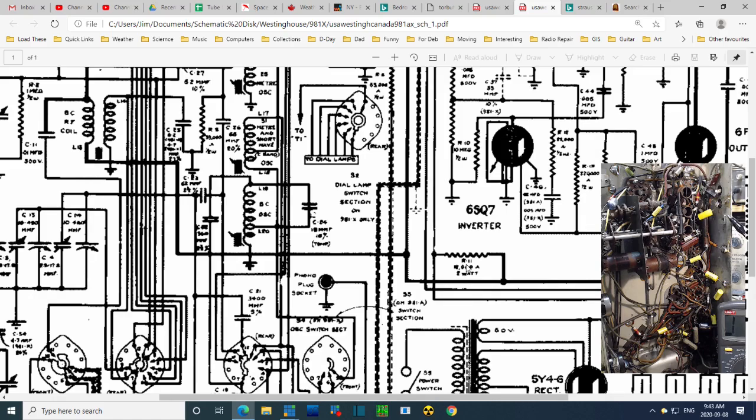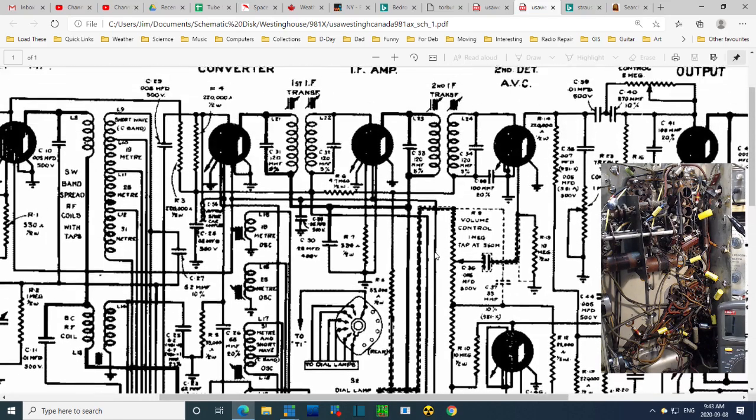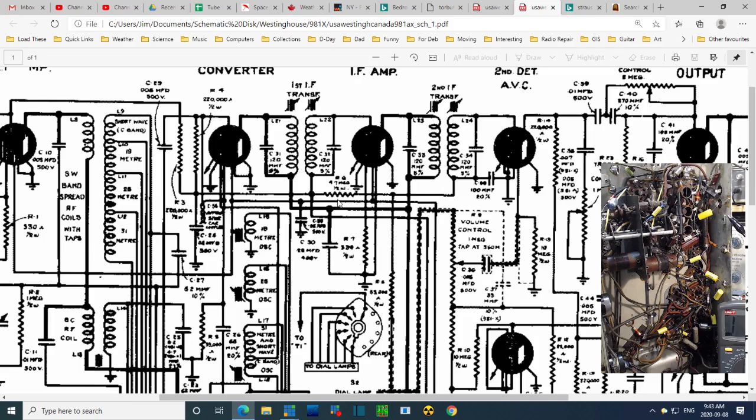20,000 ohms. Plate a screen current. Screens carry a fair bit of current. Well, you know what I could do? I could measure the screen voltage out here, and if it's low, then we take action. If it's not low, we don't worry about it. And what should it be? A sudden breakthrough here. It's not written here anywhere, is it? So it should be something a little bit less than the B+. So we measure the B+, we should find screen a little bit below it.